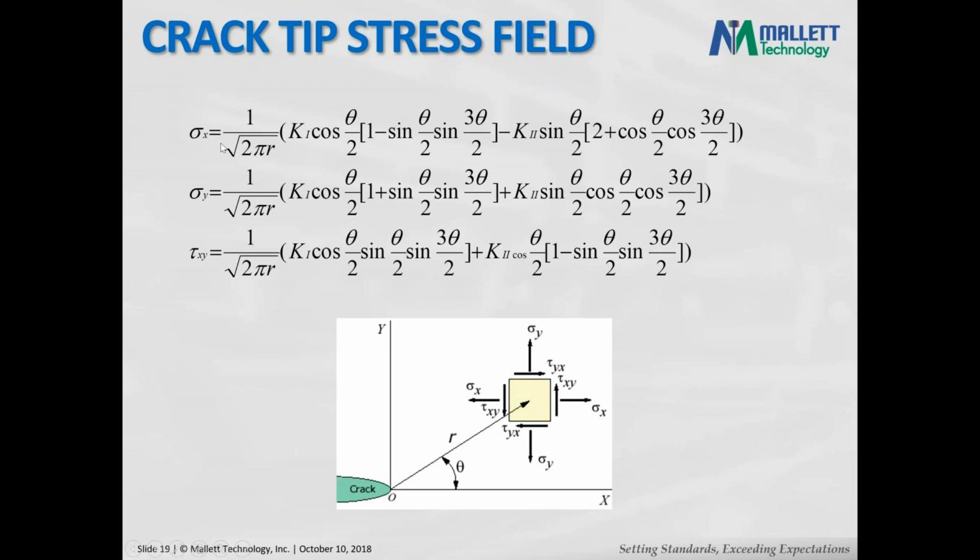How can you obtain the stress field ahead of a crack tip? Like we said, at the crack tip, the stress is singular, so we can't really calculate the stress right at the crack tip. So we are looking at stresses at an infinitesimal length away from the crack tip. Think of it like a small finite element model here: what's the stress state on this finite element model? Williams, back in 1959, came up with a closed form solution, and these constants,